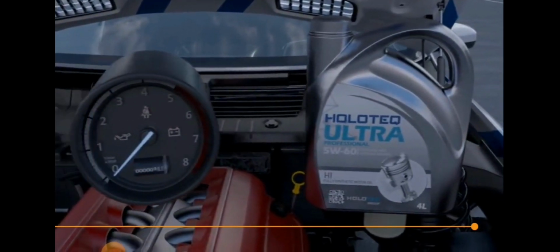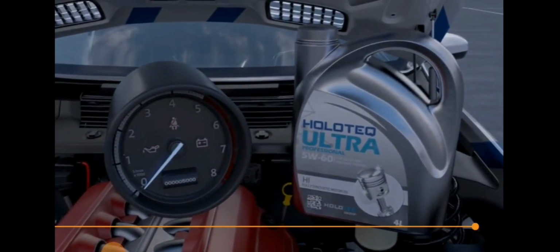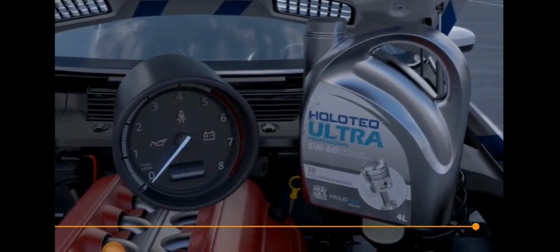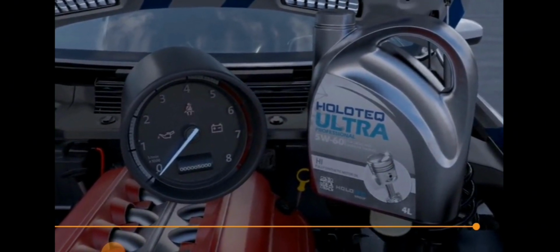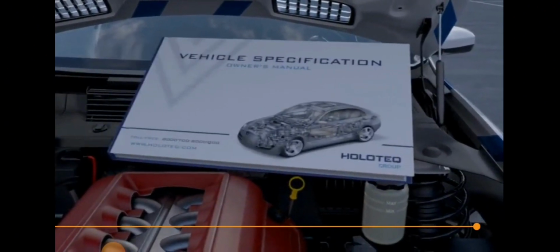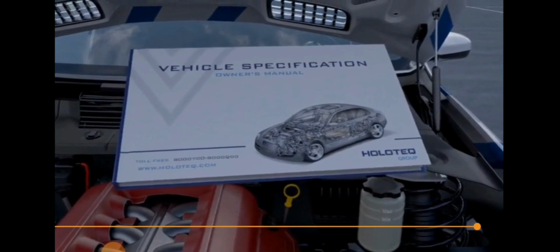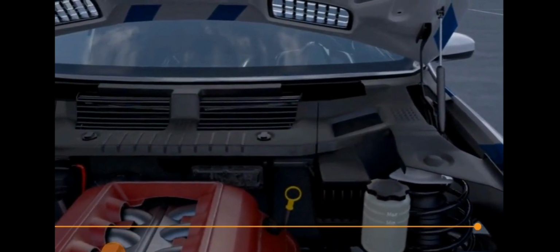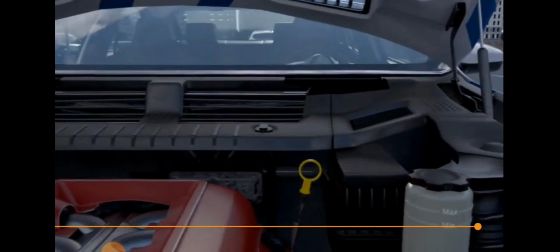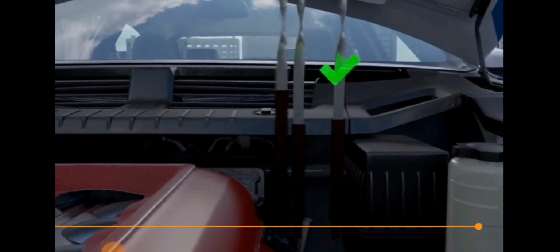Engine oil. Engine oil must be replaced in normal condition every 5,000 kilometers, as recorded in mileage meter in vehicle status panel. Specification of oil depends on instructions of vehicle manufacturer, and to make sure of the suitable amount of oil, level must be measured in the engine by oil dipstick, which indicates correct and acceptable level before turning the engine on.